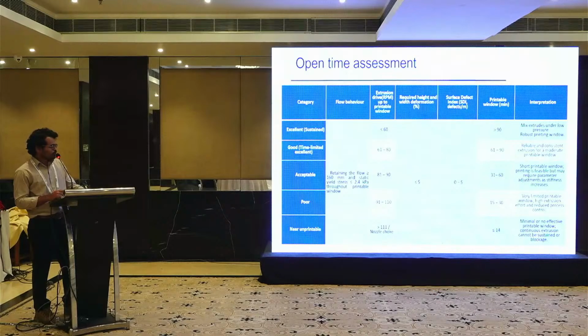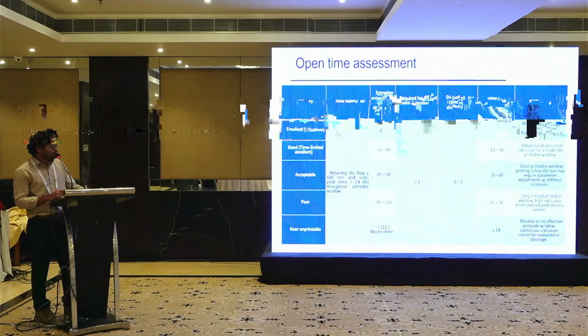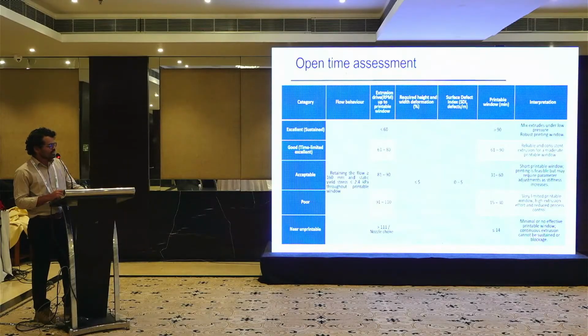So the mixes which showed flow values of 160 mm and static yield stress of 2.4 throughout the printable window, which is greater than 90 minutes, that mix is called performing excellent in terms of open time. If it is in the range between 60 to 90 minutes, it is good. If it is between half an hour to 1 hour, then it is acceptable. If it is less than half an hour, then it's poor. And if it is less than 14 minutes, it's unprintable because you don't get time to print.